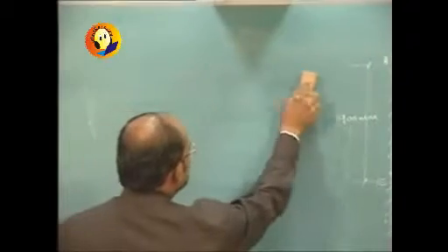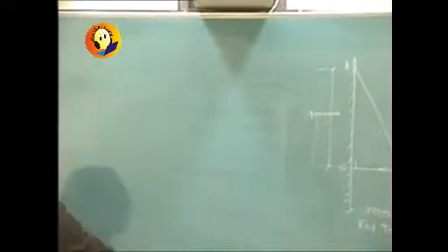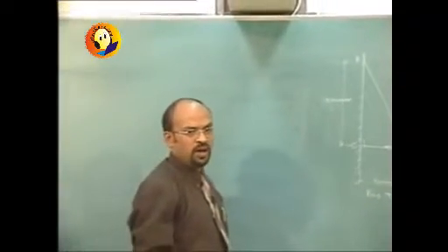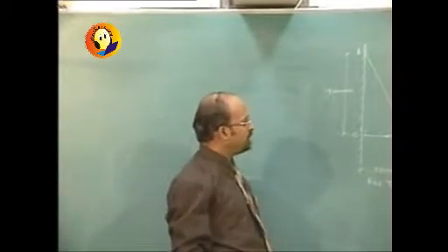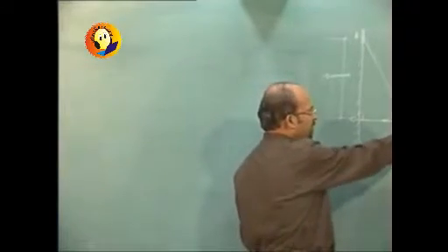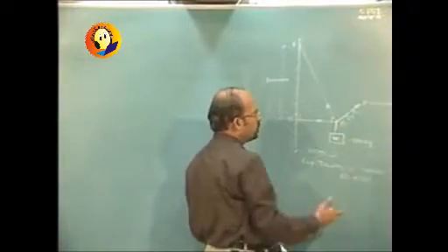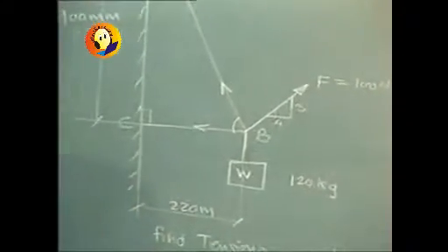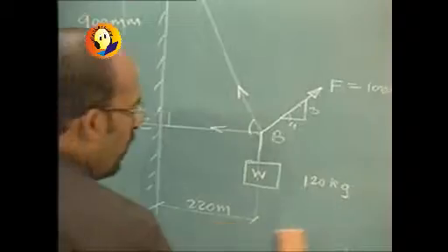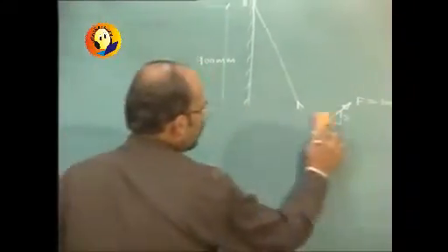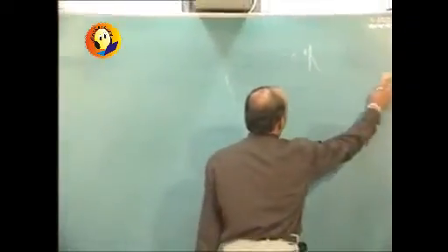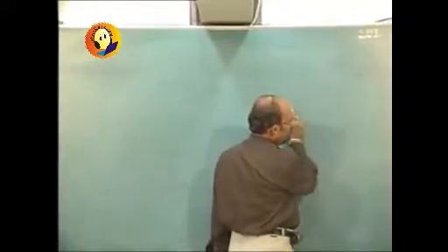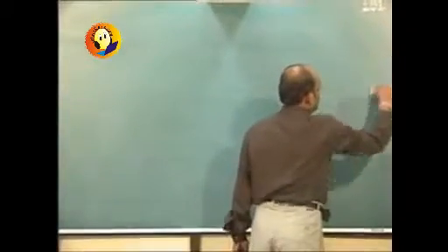I would always suggest that for more than 3 forces, instead of combining the 2 known forces into a single force and then going for Lame's theorem, as I was trying to do over here, combining W and F into a single force, that itself is going to consume more time, and so instead of that, go for sigma fx, sigma fy and find out the tensions in the 2 cables. This is a problem which is better attempted through sigma fx and sigma fy rather than the combination of Lame's theorem.